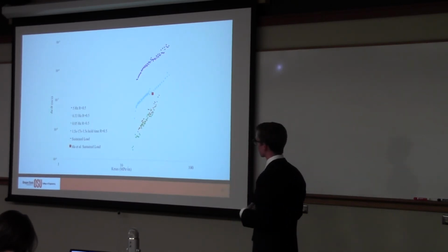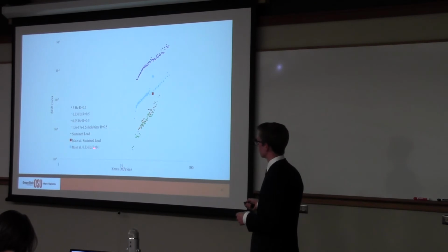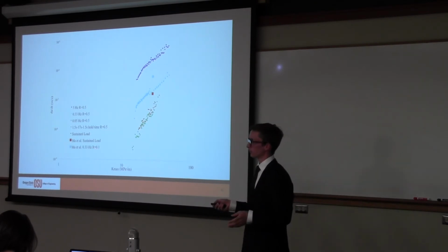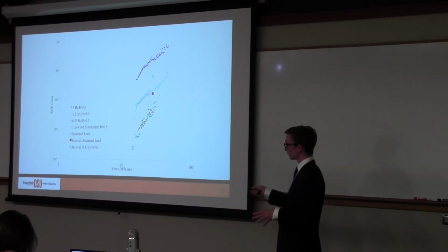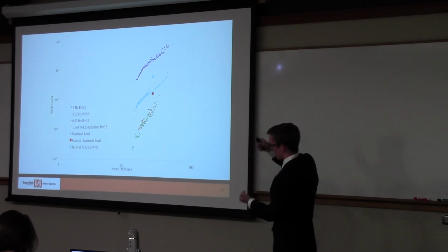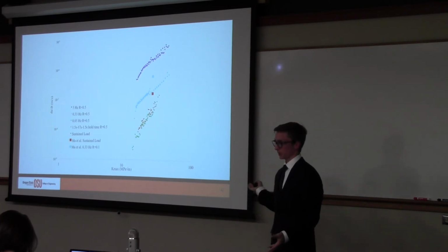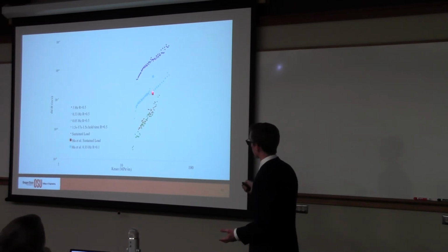Okay, so let's add another couple dots. What else did exist in the literature, and how can we compare it to what we found? And what does it mean? Ma et al. also did a 0.33 hertz sample, and they did it at a lower load ratio. So if you remember when we looked at the load waveforms, our load ratio is 0.5, and theirs is 0.1. So we went to 50% of the maximum load for each of our fatigue cycles. They went to 10%, and you expect that to result in higher crack growth rates. This is how it works. So we understand why that's higher.